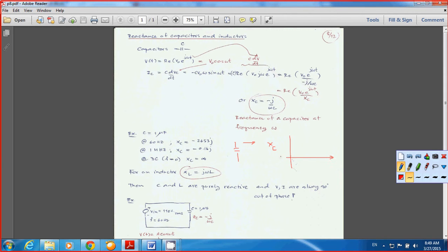For higher frequency here, the impedance of the capacitor is going to be smaller and smaller. So when you think about a voltage divider, this gives you a smaller output signal, correct? So it simply becomes a low pass filter. That means you get rid of the output voltage when you have higher frequency.